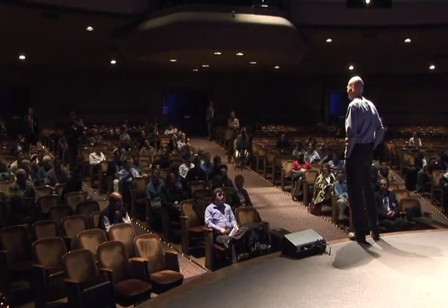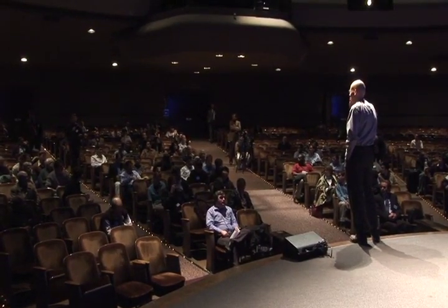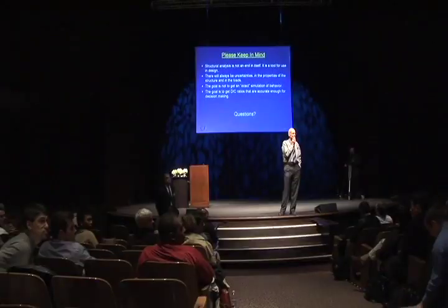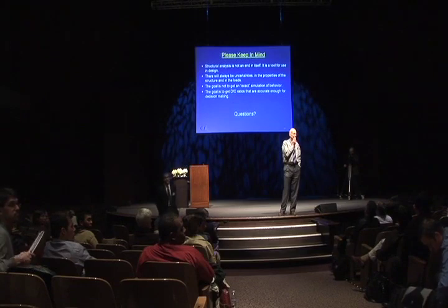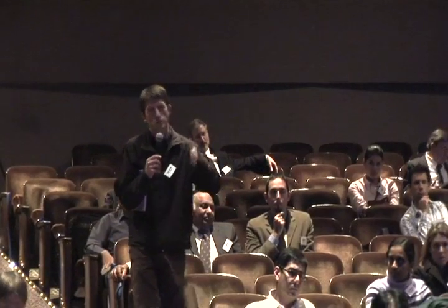Okay, and then another question regarding modal pushover analysis. In your earlier session, you talked about doing combinations. You can combine different pushover analyses to get results. For the modal pushover, you need to combine all the hinge rotations using either SRSS or CQC. Can you use the technique you were talking about earlier to do that for hinge rotations? We're actually working on it.